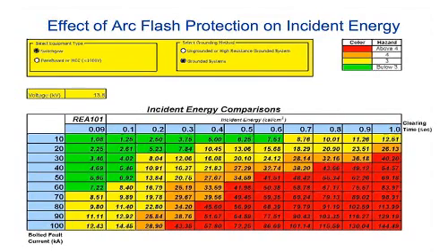Obviously, if I've got, say, a 50 kA fault, and you're clearing at 1/10 of a second, then you're at 7 calories per centimeter squared. So at this point, you're in PPE 1. Yet if you're taking 2/10 of a second, then you're suddenly in PPE 2. And it just goes worse and worse as you go down in terms of time.